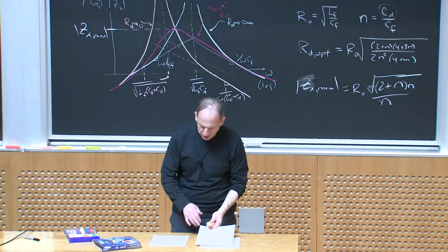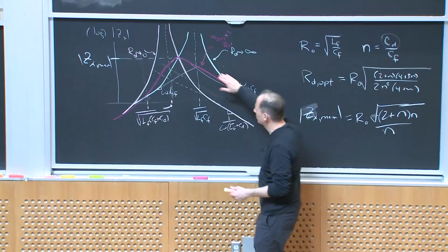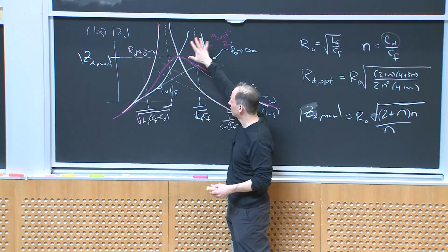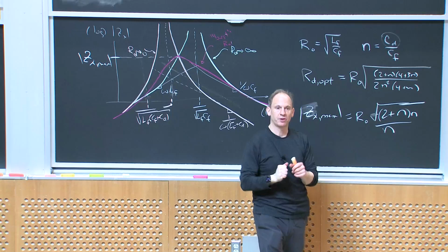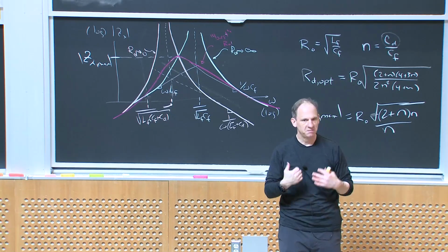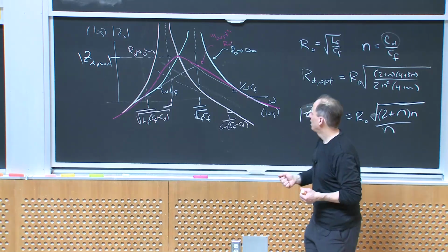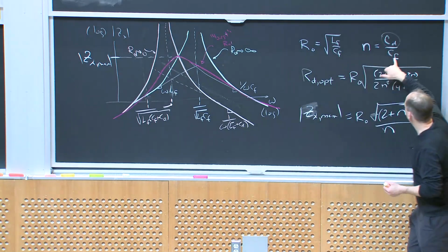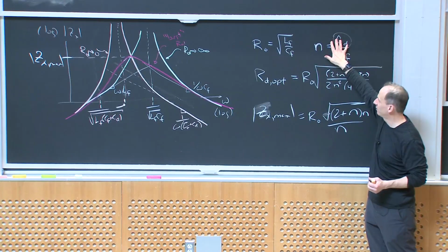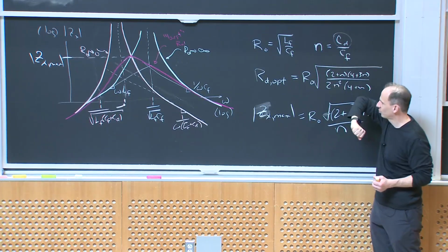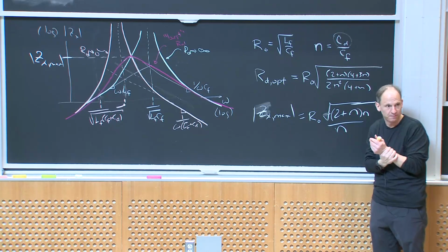All right, so what we're going to do is ask how well damped I want this to be. First of all, design my filter LF and CF to attenuate the ripple frequency. Then I'll ask how well damped I need this to be down at the cutoff. And I will say, okay, I will pick n, the ratio of CD over CF, to be big enough, and then out of this we'll get what filter damping resistor I need, and then we have a filter.